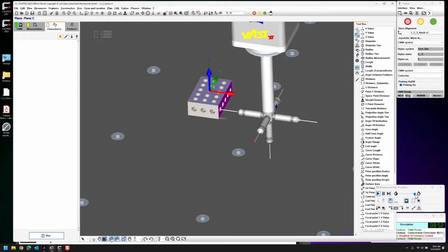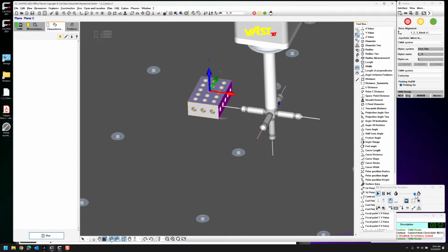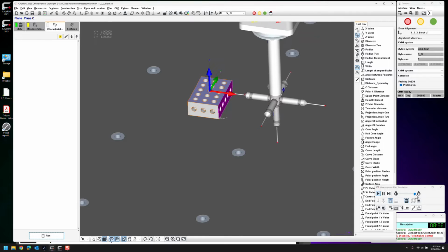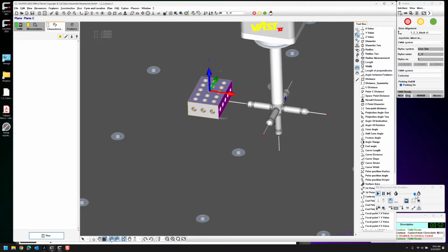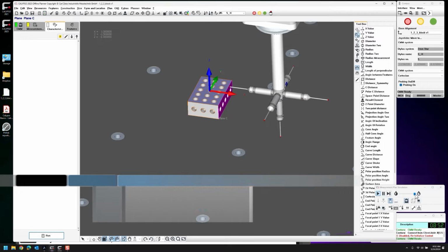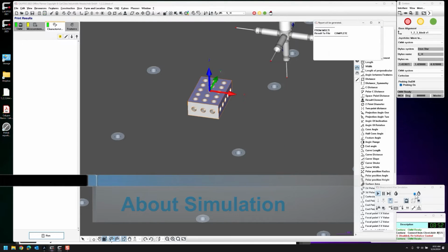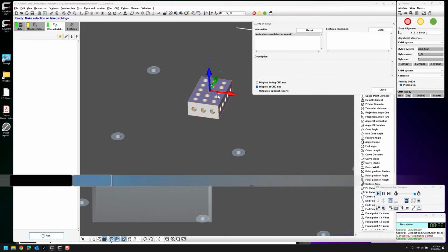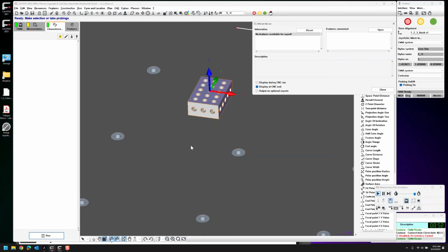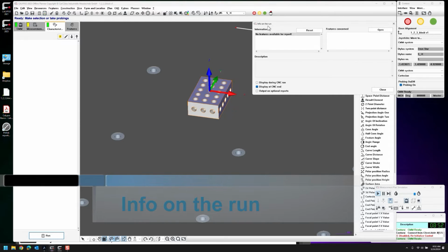And this program seems to be running quite nicely. Yep, there it is. Now I'm scanning the sides. Oh yeah, look at that. I do like having the simulation. I created the stylus using the stylus system creator. One of the important things, if you want your machine to actually show in the simulation, you have to pick a machine size that Calypso has available. Maybe in another video I'll show how to set up Planner, and I'll show you how to determine what that is.